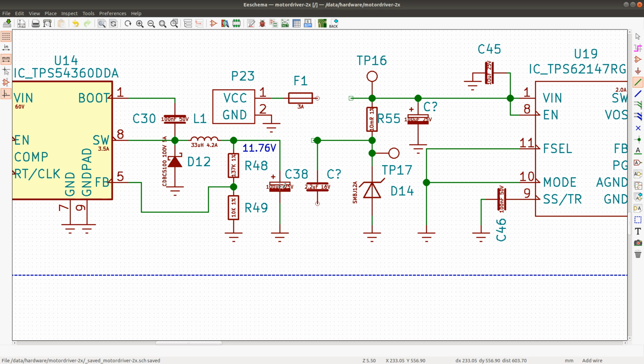But because capacitors degrade, we don't need to really take that into account. This capacitor will probably degrade to like 90 microfarads or lower. I'll use the same value for the ESR as they used, like 25 milliohms for now.